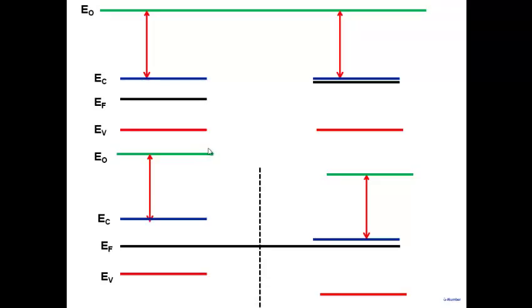We don't know the exact variation. Energy band diagrams don't give you quantitative information on how it goes. For that, you'll have to solve Poisson's equation. Okay, but we can connect this up. We can connect through a smooth curve here like this. All right. Now, once it goes like this here, how will this go? This is always below vacuum level by electron affinity. So it will also go like this here. And it will also go like this here. And our energy band diagram is complete. We have a complete energy band diagram at equilibrium.